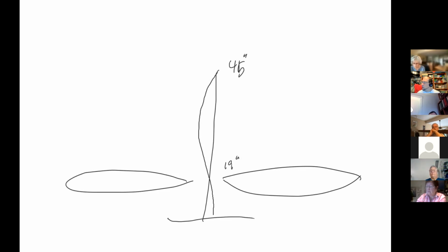So why would you choose one over the other? A 5/8 wave gets out better if you're out in the middle of nowhere. With 19 inches, it doesn't smack against your garage when you pull in. I can go through drive-throughs. I can pull into a parking garage. I don't have to take the antenna off. Whereas if I had the bigger one, it would constantly keep hitting things.